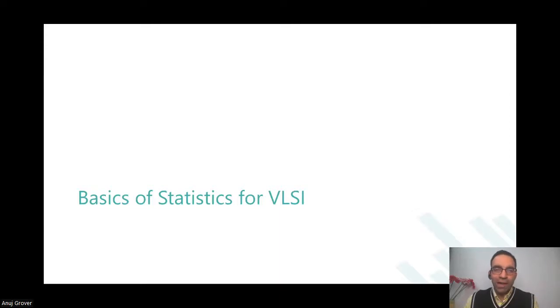We don't talk about it as much in the analog design course, because there are trimming bits, there are reference currents which you would trim, and you would bias the circuit again to the desired point. In memories, you do not have that kind of flexibility, and therefore statistics become very relevant. In reality, the same statistics you can apply to any other circuit also. The only thing is that those circuits are not repeated as often. You don't need to go to Six Sigma extents, as we will just see. Okay.